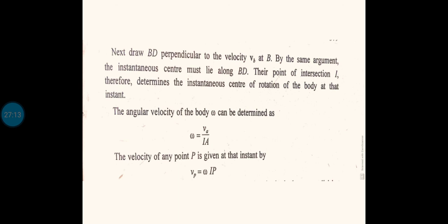The reason we can apply this equation is that for a rotary motion the angular velocity remains the same. Omega will be equal for all the points. That is the basis of using this equation to identify the linear velocity at any point. Okay, I think the concept is clear for you. Now in the next presentation we will be seeing problems related to all this.